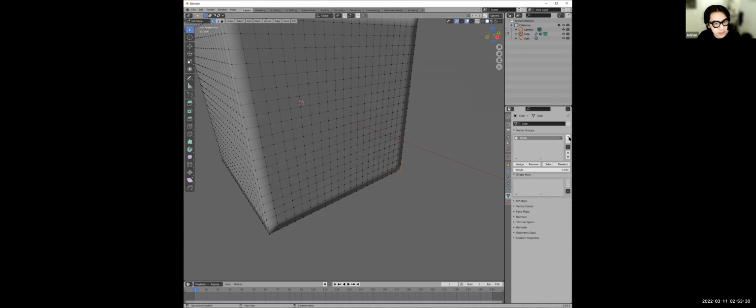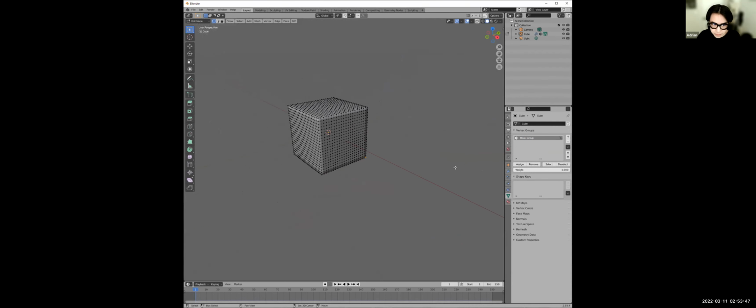And then we will click plus on this vertex group. We will make sure that we click assign to make sure it's assigned to that group. Make sure you click assign. We'll double click this one and we'll call it something different. We'll call it hook group, for what you're about to see. The command that we'll do is actually called hooking.